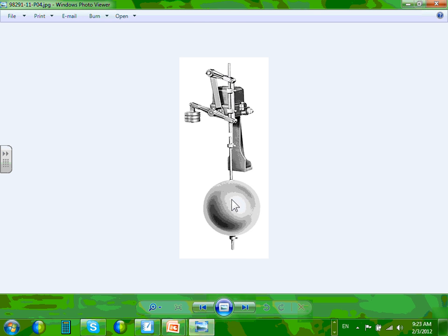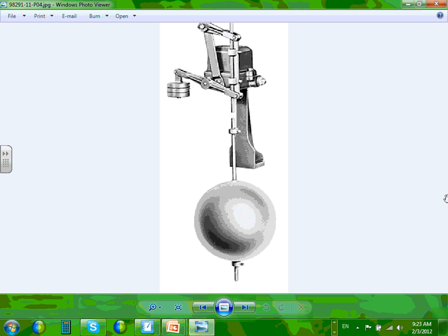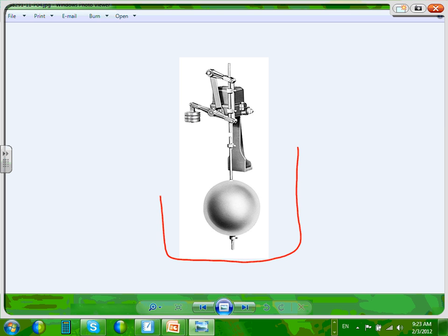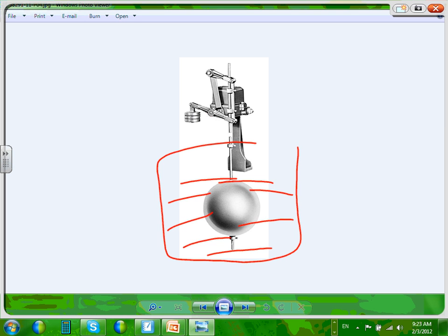Nick, this is your float switch. Obviously, you're not going to bring the power into that water. And I don't want to talk about the pilot devices, guys. It fills up with water and moves that ball up. When that ball moves, there's a contact here that will mechanically close. These are called pilot devices. Close the contacts, and now you energize the sump pump. Any comments, any questions, guys?